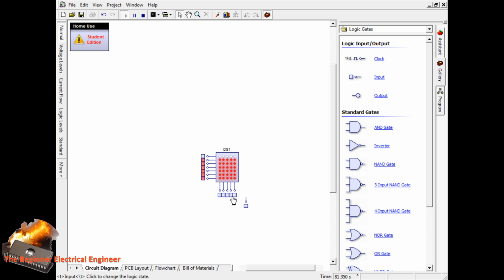Now, the reason why you multiplex is to get rid of all of those unwanted LED flashes that essentially make that big square happen, because multiple LEDs are allowing current to flow when you don't want them to. So multiplexing simply is you turn on one column at a time, and all of the LEDs, or the rows that you need, and then you turn everything off really quickly.